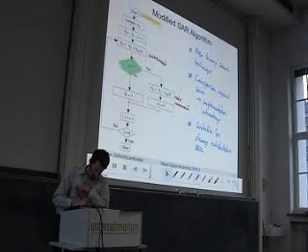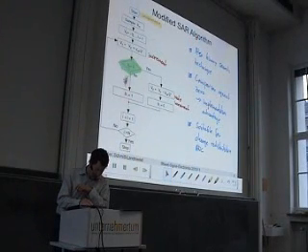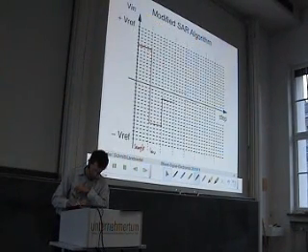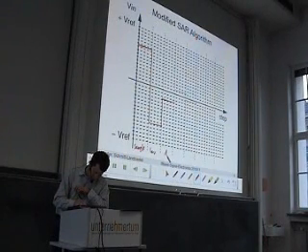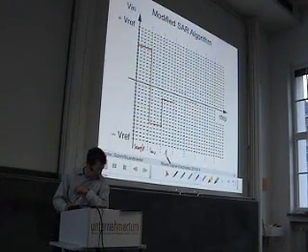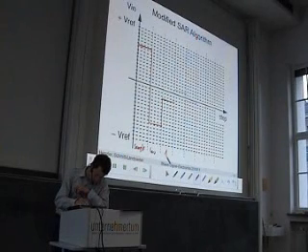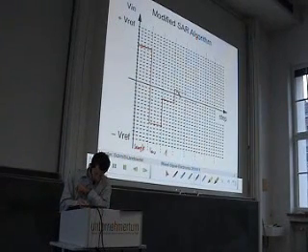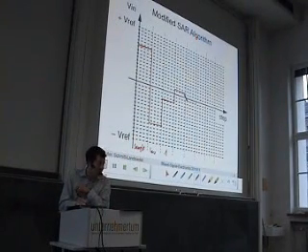Hence we go for this branch. So we do not undo this increment, we keep it, and we set the bit to 1. So we set this to 1, and now we increment again, however by half the value, and you can see now we cross the 0 line and become positive.